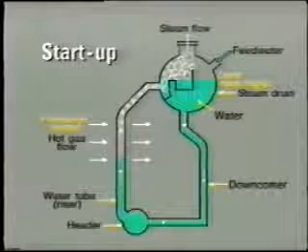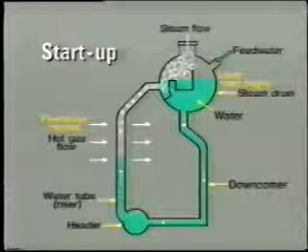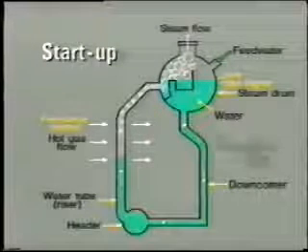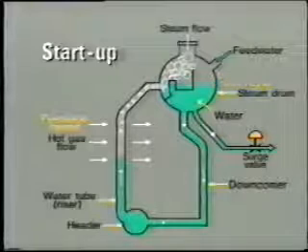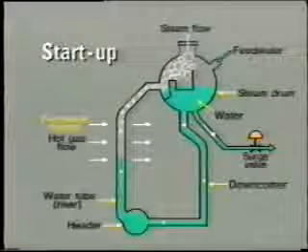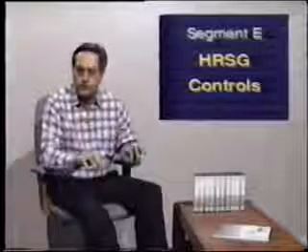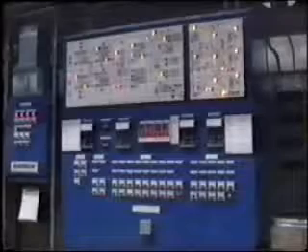In order to prevent water being carried over into the superheater, the water level must be reduced by draining water off from the bottom of the drum through the so-called surge valves. These valves may also be called blow-down valves, but this term is usually reserved for the continuous blow-down, which controls conductivity in the boiler water. Let's look at this item.